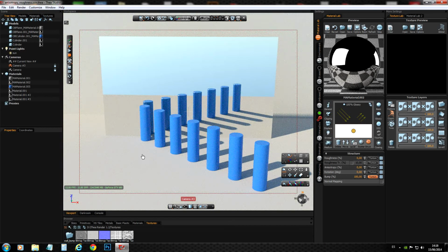So right now we have a roughness of 0 and no anisotropic, so you can see it's a clear mirror. Let's add a value of 10. And we can see our reflection gets stretched vertical because the grooves are horizontal. But you can also see that we don't get any blurring in the horizontal direction.